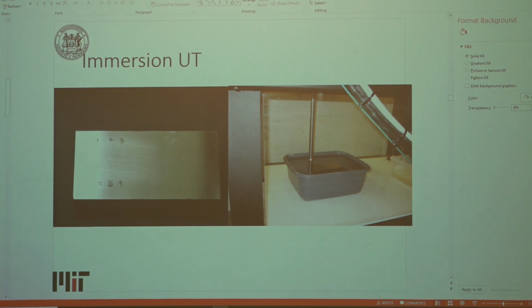For the NDE industry, what they generally use is called FBH, flat bottom holes, which go by 1/64 of an inch. Below that, 1, 2, 3, are laser drilled holes into those samples of various flat bottom hole sizes. So this is essentially a calibration block for that material.